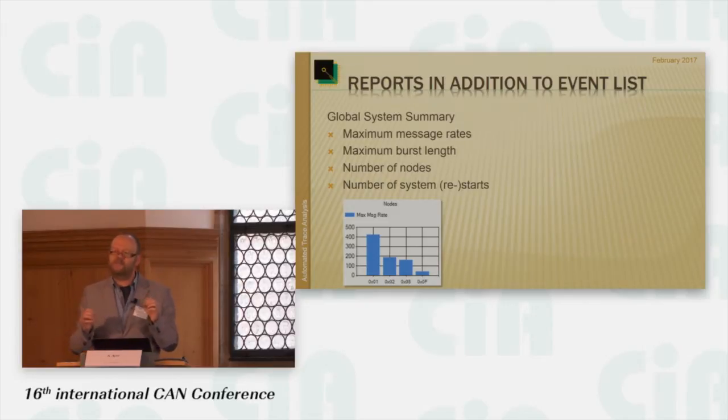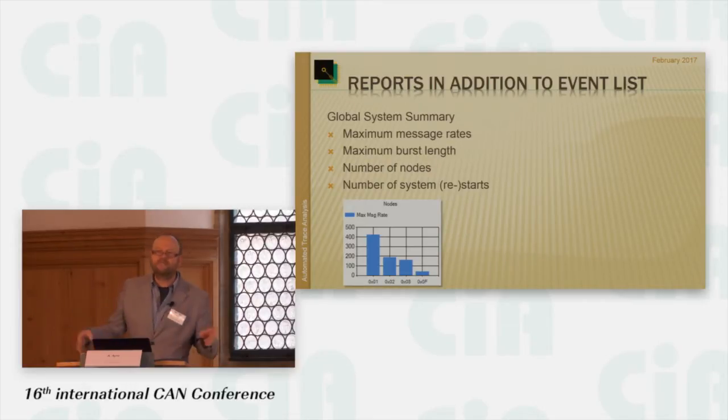And if you measure this in a system, you know this is the maximum delay of your lowest priority message, because as long as you have back-to-back CAN traffic, any lower priority message would need to be delayed. And if you, for instance, measure for a longer period, and my maximum burst length was never more than 6 milliseconds, then you know even the lowest priority message would have gone through within 6 milliseconds. So this is really a number I like a lot.